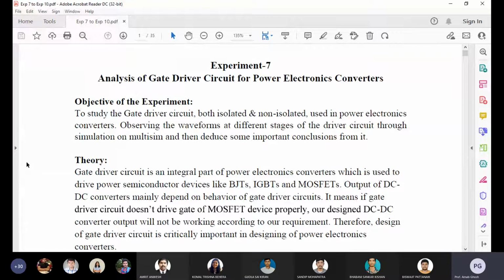That's why, when we collect the output voltage from our power circuit, we use transducers. What kinds of transducers do we normally use? Hall effect transducers. We isolate the control circuit from the power circuit when fetching the actual voltage, through magnetic isolation, using Hall effect sensors.